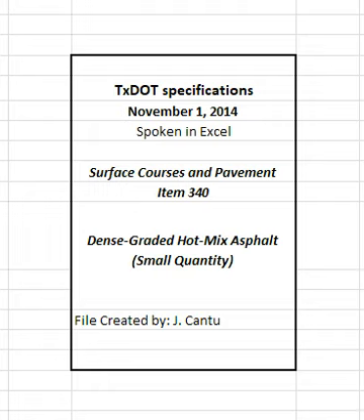Take immediate corrective action when the in-place air voids exceed the range of 3.8% and 8.5% to bring the operation within these tolerances. The engineer may suspend operations or require removal and replacement if the in-place air voids are less than 2.7% or greater than 9.9%. The engineer will allow paving to resume when the proposed corrective action is likely to yield between 3.8% and 8.5% in-place air voids. Areas defined in Section 340.9.2, miscellaneous areas, are not subject to in-place air void determination.